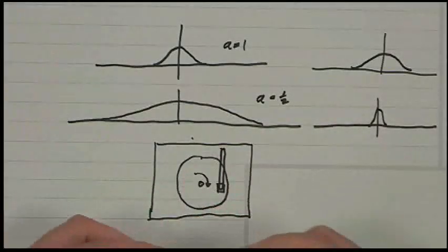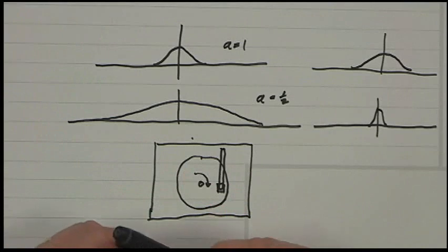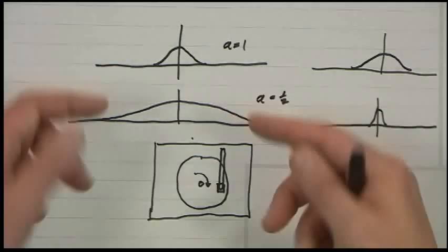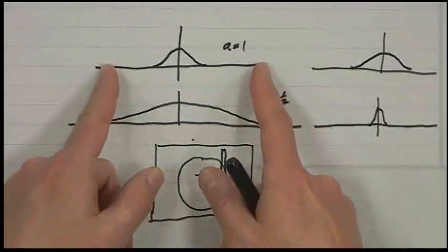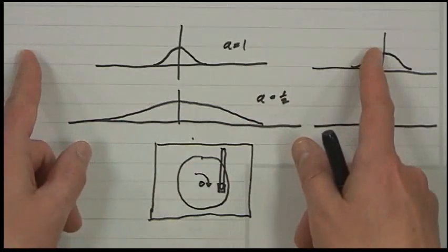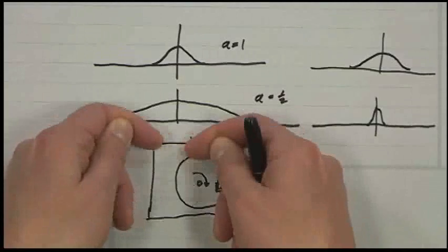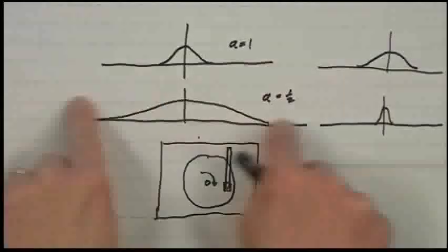If you really learn this well, you will have acquired a very valuable piece of knowledge which will distinguish you in the workplace. Because most people never really understand this. There's a few basic things that signal processors understand that a lot of other people don't understand. They don't understand this, and they don't understand the sampling theorem. It's actually pretty counterintuitive that as you squeeze things together, we'll see that in discrete time, when we take a larger window, we get finer sampling in frequency. So stretching in time tends to compress in frequency. Compressing in time stretches in frequency.